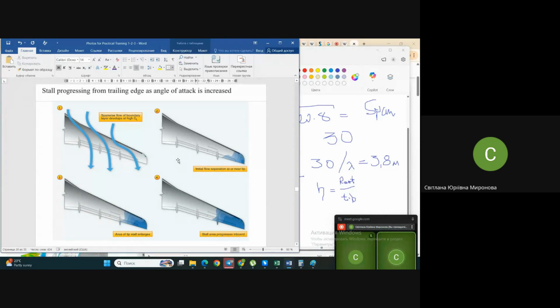If you have variance, maybe use swept wing. Again, this is the angle of sweepness, the angle between the horizontal line, the lateral axis of the airplane, and the leading edge. It's also designated with a Greek letter in our literature, as you might see in Fedotov's book, and it may be very different for different airplanes. Once again, the more speed, the higher this angle.